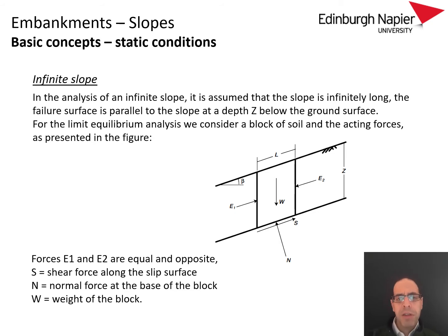And the key of the limit equilibrium method is that all we need to do is assume a failure surface and then calculate the equilibrium of forces along that slip surface and in perpendicular directions to that slip surface. So you can see that that is what we are doing in this situation.